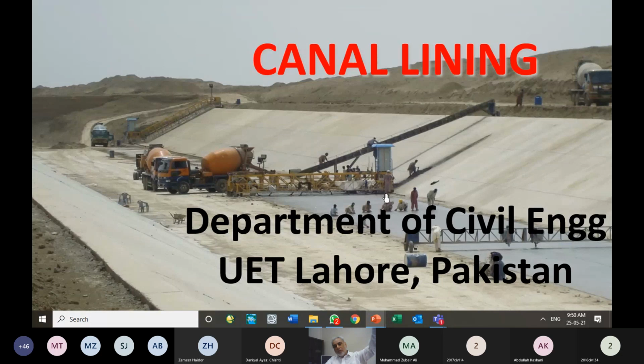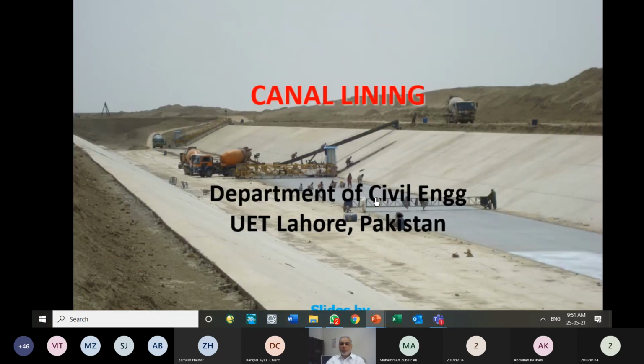When you have to carry out the work on a longer dimension structure like the lining, like you have to construct the parapet of a road, तो फिर आप slip form work is a good thing. So ये slip form work is being utilized over here, and they are providing the material with the help of the concrete mixer. It means they have a concrete mixing plant somewhere, or from there they get the concrete, ready mixed concrete, they place it. So this slip form will give it a proper shape, compact it, and then move ahead. So this is how usually a large project lining is carried out.